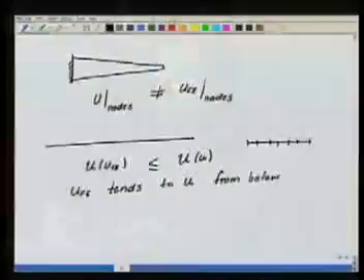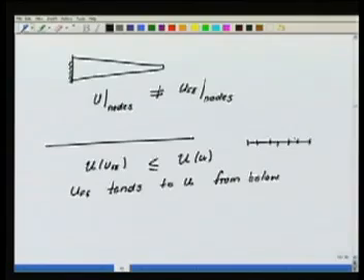So if I am able to compute the strain energy of the finite element solution, then if I take a sequence of meshes, that is I take a mesh which is a crude mesh, maybe this one, then I refine the mesh, then I take the sequence of finite element solutions, I should get that the strain energy for the crudest mesh is lesser than the strain energy for the next refined mesh, which is lesser than the strain energy for the next refined mesh. So this is what we should be able to observe. Okay.